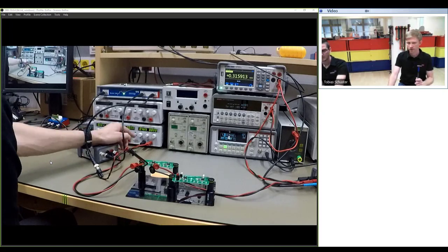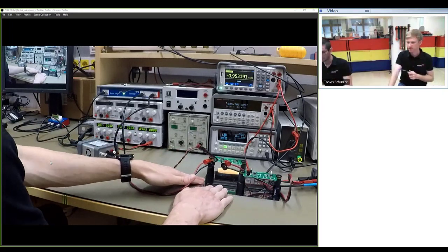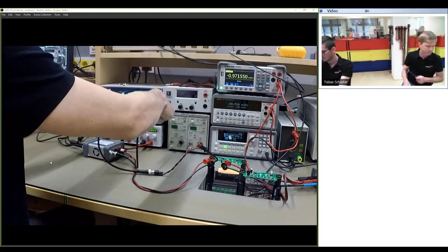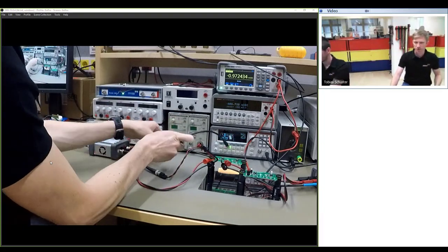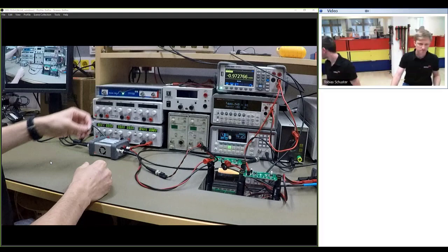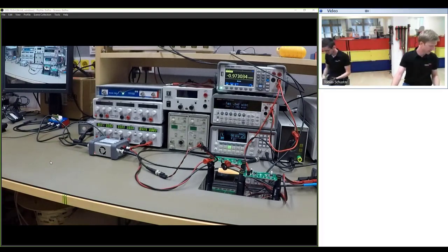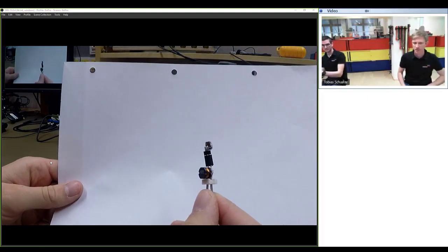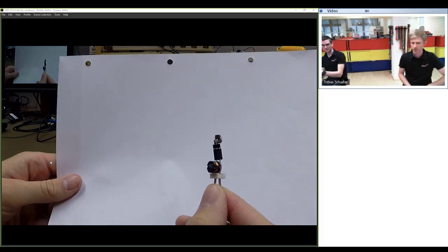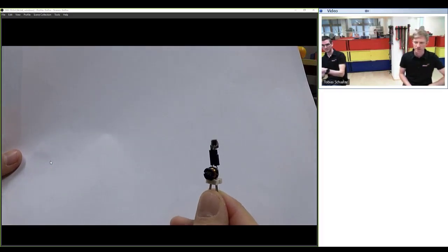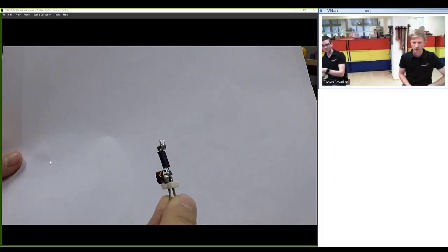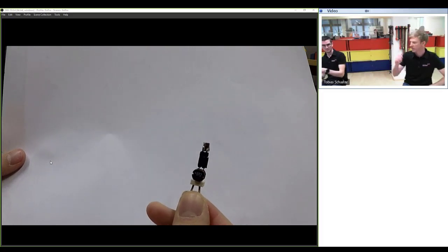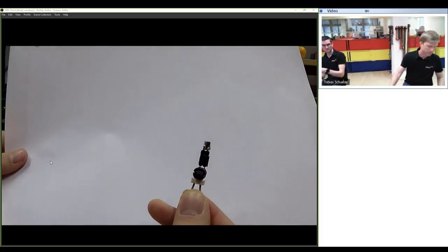And you can now turn off please and take away the setup, and the next thing we're going to do is measuring the filter that we're going to add. Can you please also show the filter to the camera? So I'll bring on the filter. We have made a little second filter where you can see the inductor and the capacitor in the back of the inductor. So that's the LC filter. There is a ceramic capacitor and the inductor and the damping network on top that we can take off using a little jumper.